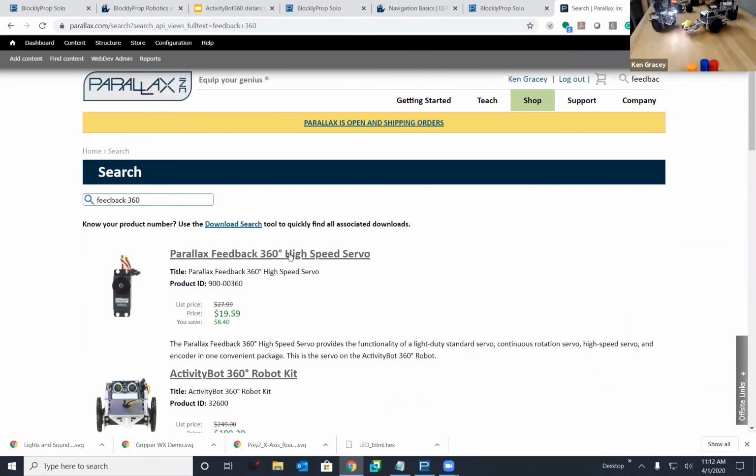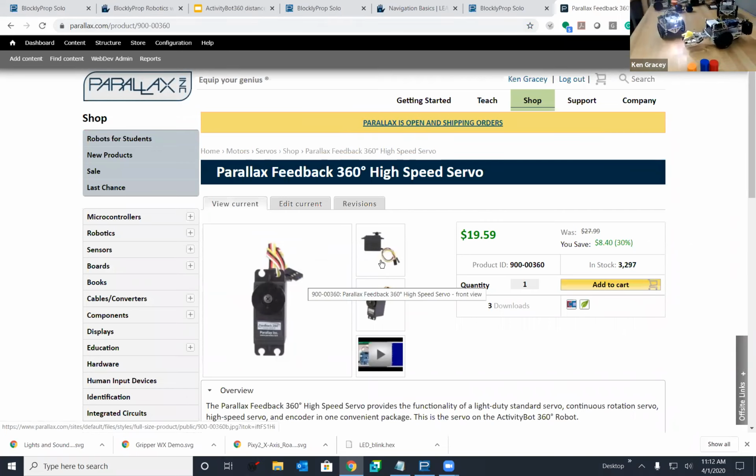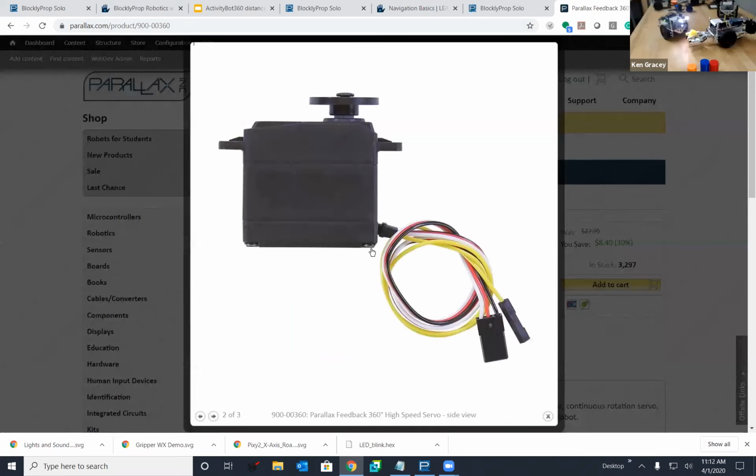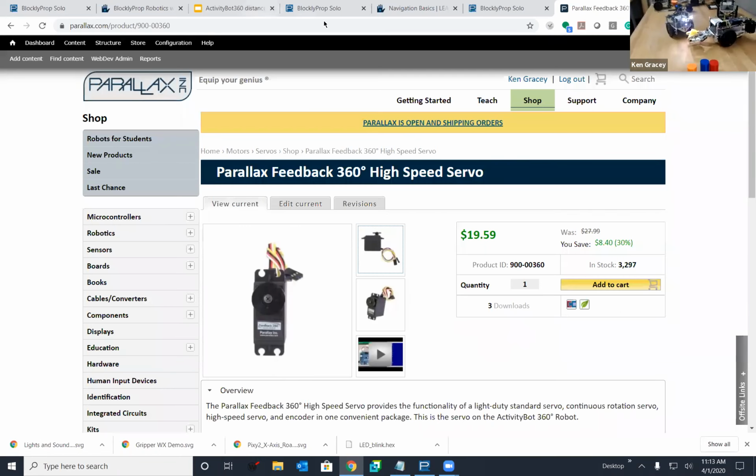And this servo has on it this yellow line that you hooked up, and that yellow line gives a signal back to the propeller activity board, and our library is doing some calculations to allow you to specify distances and speeds because of that. And this is a huge boost to be able to drive centimeters, clicks, ticks, or whatever you choose, or inches with the robot. And it's fairly precise too. So not available in other robots, and the complexities of it are absolutely abstracted for you.